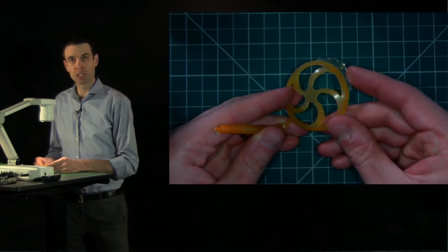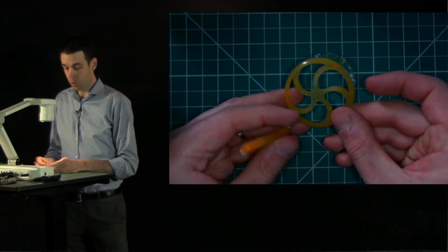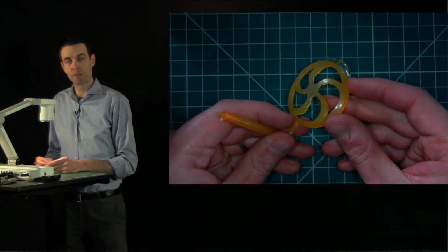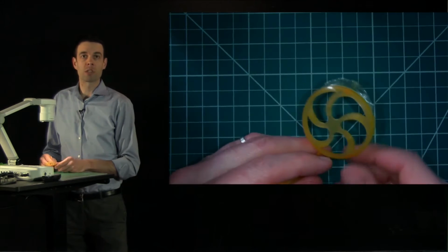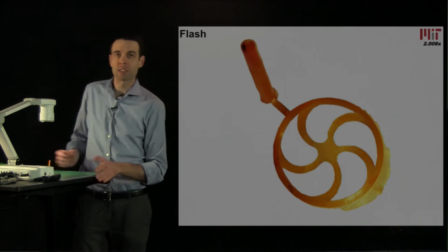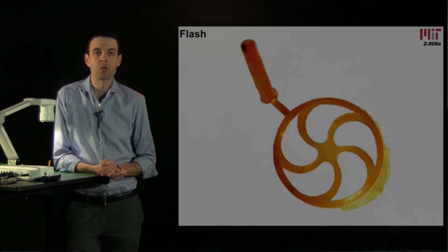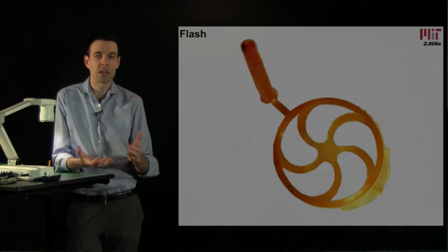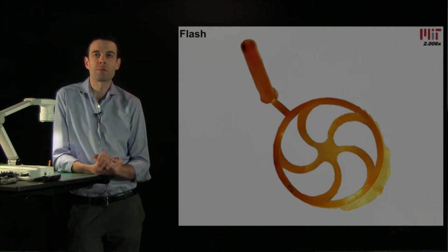And therefore the process parameters or molds would have to be edited to remove the flash, or if you can't get rid of the flash, you have to take it off after the process. And you might also have come across parts that have flash on them, and parts that you buy with flash, and that's, for example, a low-cost clothing hanger, and there's really no driving force to make the part better quality. If they can make it cheap and functional, in some cases that's good enough.